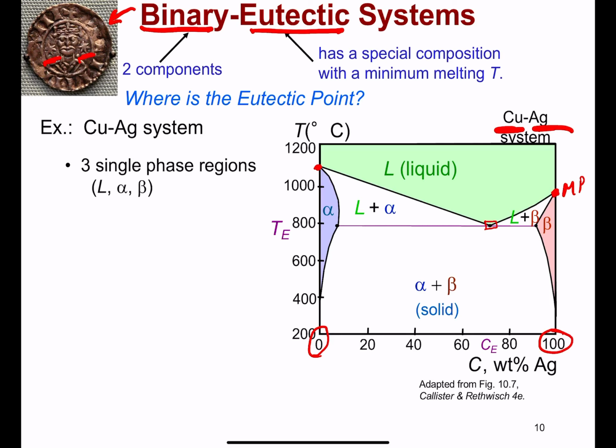So the types of phases present throughout the composition or phase diagram: we know the liquid. We saw that there are two solids, an alpha and a beta form. There are also some other territories in here. We have an area where there's liquid and alpha in this white wedge area. And complementing that, across the liquid to the other triangular area, we have a liquid and a beta phase.